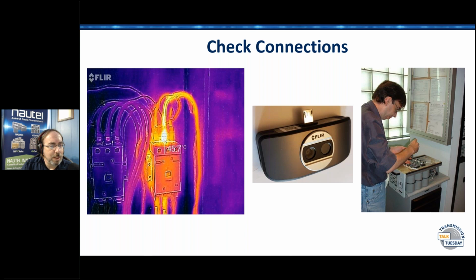One of the big things that I tell people they should plan at least once a year is an inspection of the ground system. And the big challenge with ground systems is, of course, they're typically underground, so they're a little harder to see. Especially for those of us in areas where the ground does tend to freeze, you'll get frost heaves, unless your entire ground system is more than 3 feet below grade. And even then, you're still going to have rocks migrating.